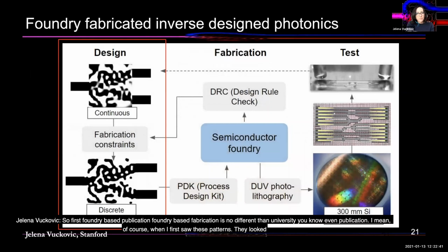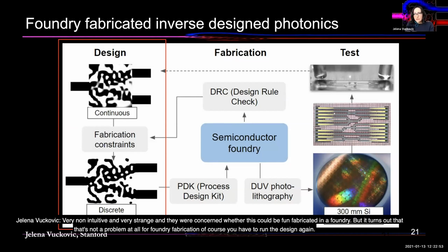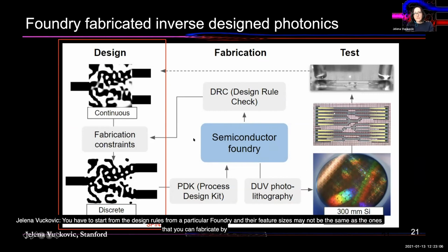So first, foundry-based fabrication. Foundry-based fabrication is no different than university e-beam fabrication. Of course, when people first saw these patterns, they looked very non-intuitive and very strange, and they were concerned whether this could be fabricated in a foundry. But it turns out that that's not a problem at all. For foundry fabrication, of course, you have to run the design again. You have to start from the design rules from a particular foundry, and their feature sizes may not be the same as the ones that you can fabricate by your electron beam lithography. And in fact, that's usually the case.